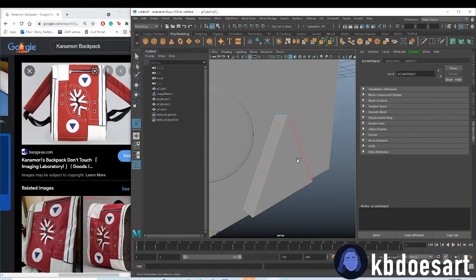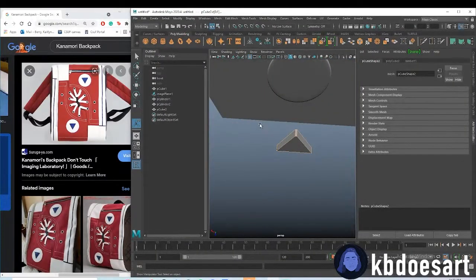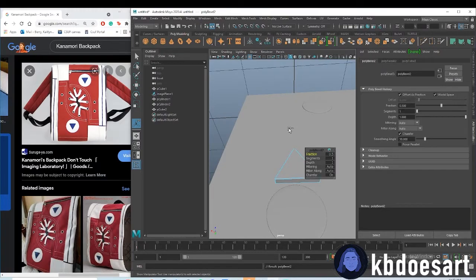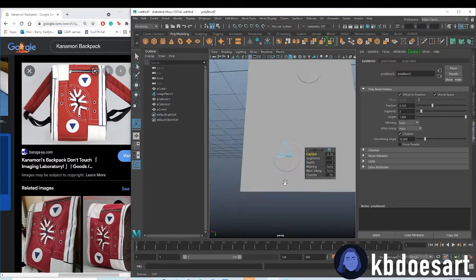I want you to select every edge of this triangle, which I guess you could also just do by literally clicking and dragging. And then do Control B to bevel it, and then do 2 segments at a pretty small fraction. And it should get that.